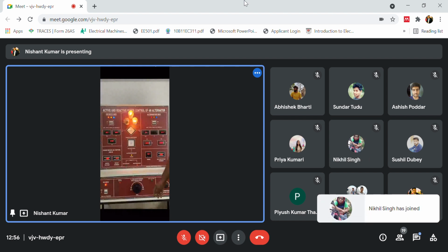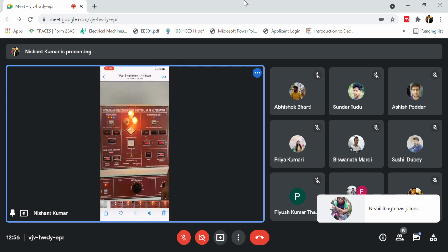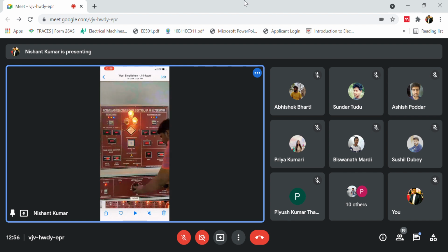and residual current. Next, we start rotating your alternator, which means we are providing the excitation. Whenever you provide your excitation, you could assume there would be a pressure on your prime mover, which will tend to decrease the speed. So you have to maintain that particular speed also. Okay, the speed should be maintained. So I am controlling both units and I have to maintain that.